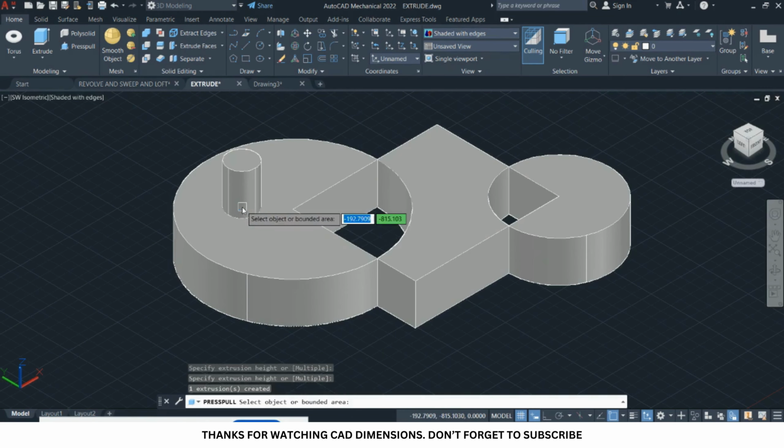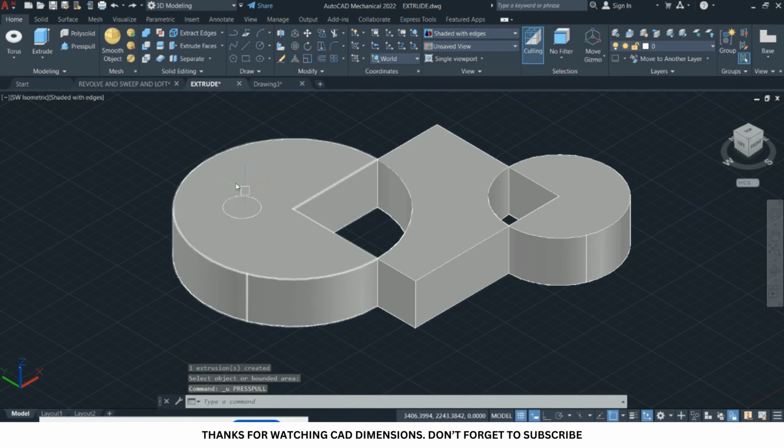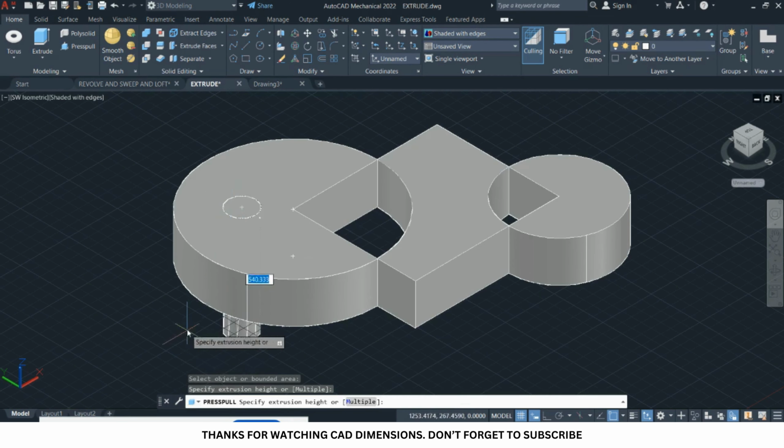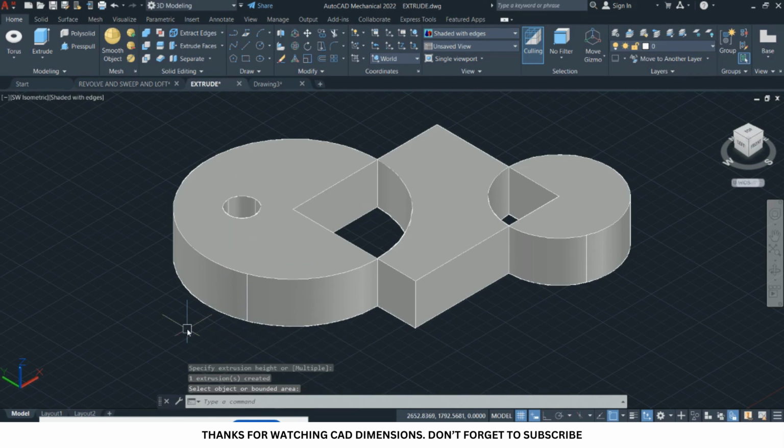So let me go back. Select press pull, then select the region. Okay, then you can drag outside or downwards, and then you'll be able to create a hole. So the press pull helps you to create extrusion. We can also create a subtraction from a particular model, right?